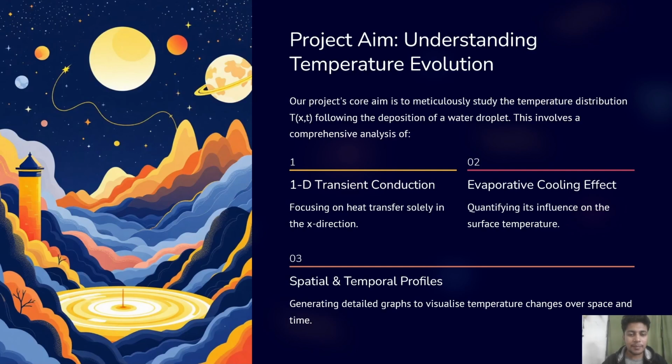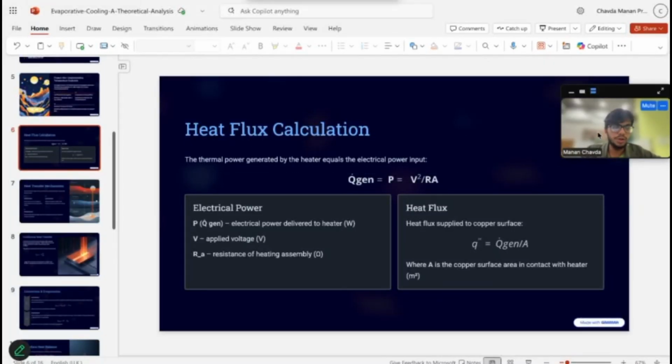These are the main physical parameters defining the thermal behavior. The copper block starts at 55 degrees Celsius. Copper has high density, about 8960 kg per cubic meter, very high thermal conductivity, about 400 watts per meter Kelvin, and a specific heat of 385 joules per kg Kelvin. This high conductivity and moderate heat capacity strongly influence the speed at which the cooling front spreads through the metal.